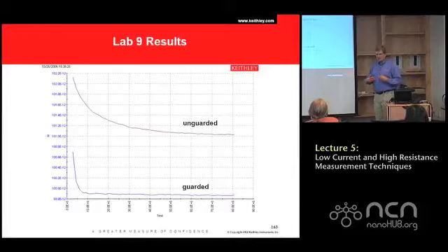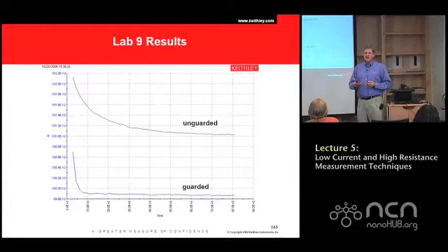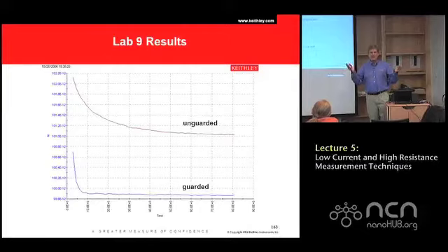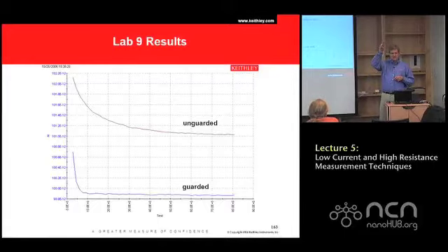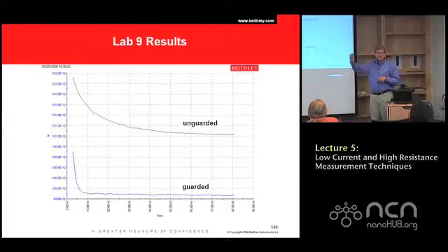Now, I personally have a test that I use that I call the step function test. I use that to give me a measure of the efficiency of the guarding in my system and how well my system works. The step function test is very easy. I use the custom list sweep capability. I build myself a 100-point sweep. The first 10 points are at 0 volts. Then I step to 10 volts. And the next 100 points are at 10 volts. And I measure the current.